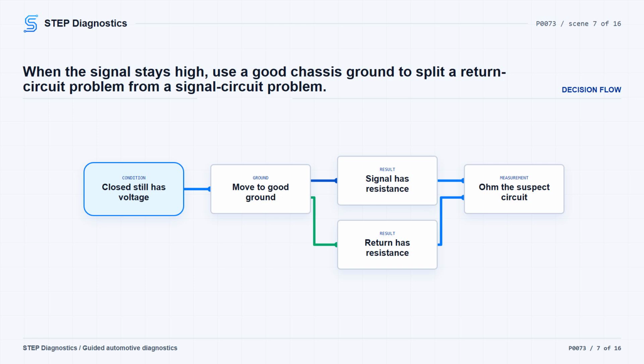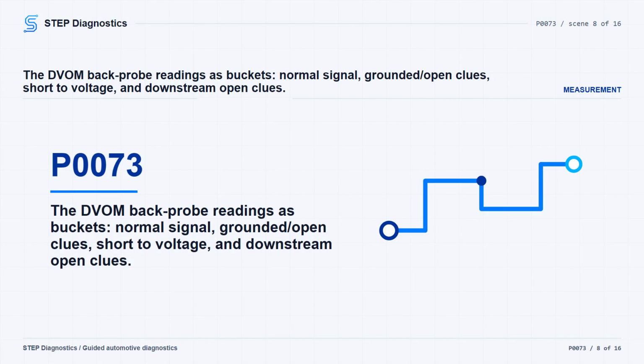Check the correct circuit for high resistance. Typically, it should be less than 3.0 ohms. If the circuits are not excessive, check every related connector for pushed out, spread, corroded, or dirty terminals before condemning the ECU. If you are using a DVOM instead, keep both the temperature sensor and ECU harness connectors connected and locked.